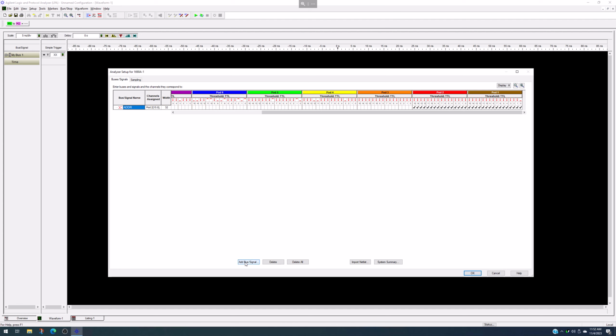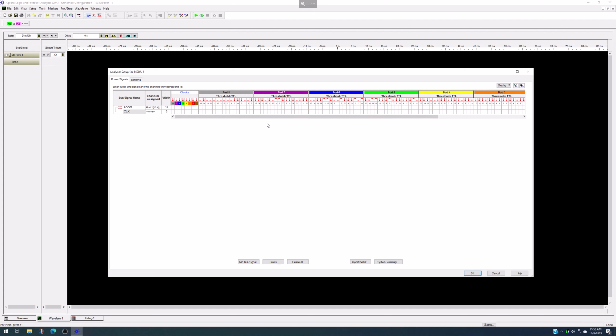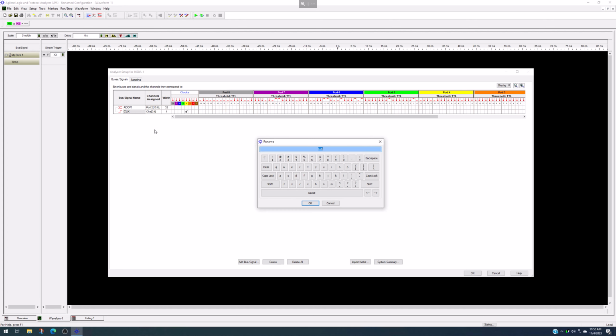And then I might also say, well, I'd like to add in a clock signal. So let's add clock, and then I choose clock and say OK. And then my clock, I can choose where to pick it up. Each of these little acquisition boards I built does have a jumper, and I can pick off of clock 2 or clock on my 386, on which one it feeds over. And I can read those independently over here. Clock 2 I have configured currently to be coming in right here, and so that's actually clock 2. So I might rename this to clock 2.